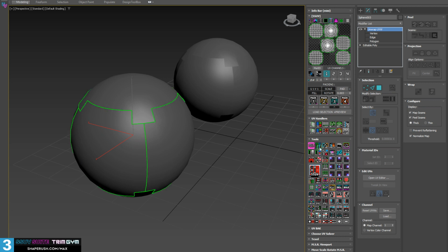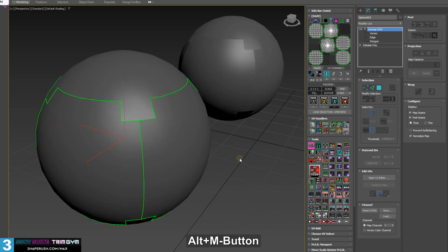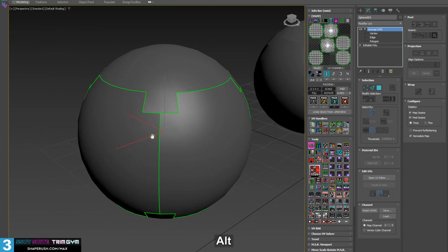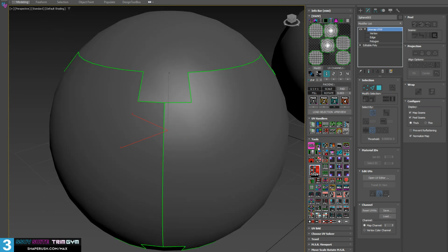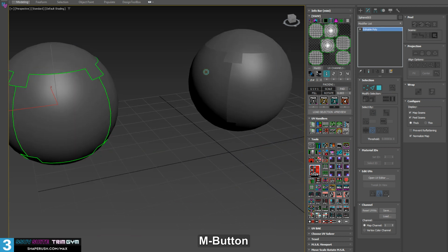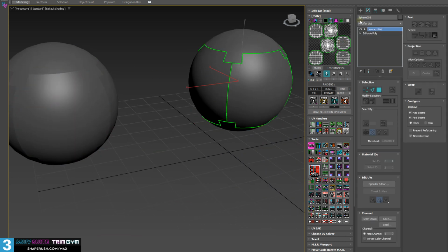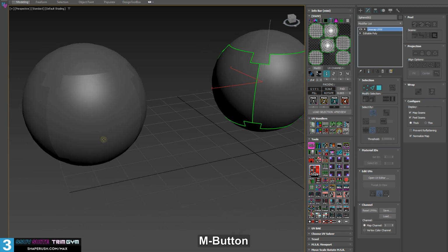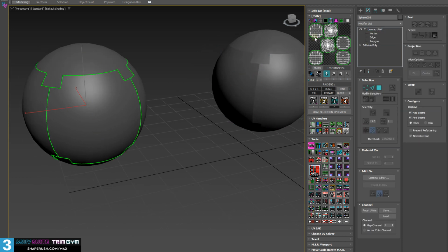So if I left click, I cycle through the different seam types, and if I right click, I see thin and thick, right? I'd like to keep it on the thicker seam because it is easier to see in the viewport. All right then. Same with backface, we can turn that off, select another object, load that object into the system where we see backface is on, and if I select this object and load it into the system, backface is off.